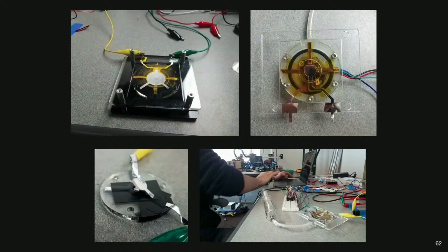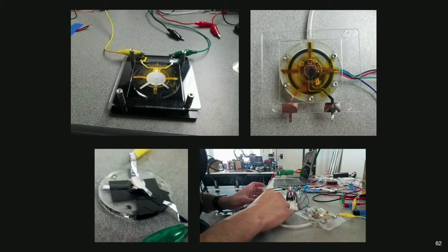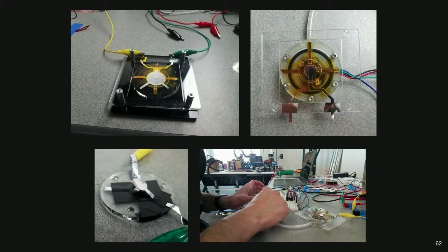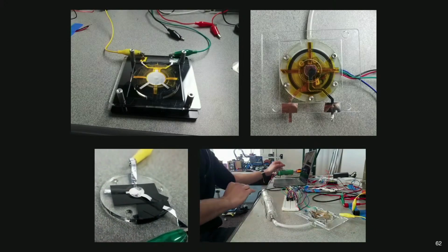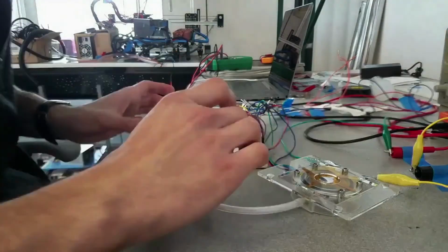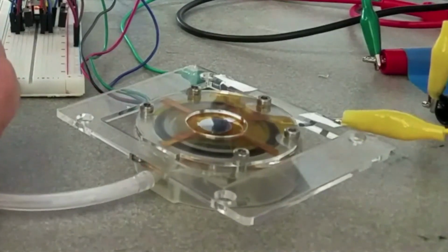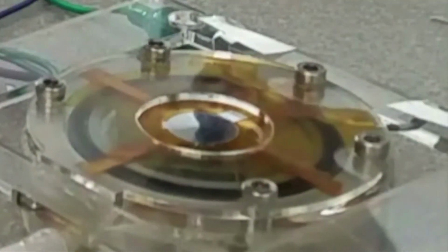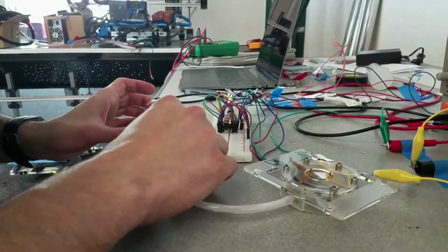Cool. Now, since this is the Hackaday audience, I wanted to talk a little bit about the process of getting here, because we're actually doing something that's a little bit unconventional with the valve structure. So initially our idea was to use these mylar diaphragms as lids. Here you can see I've got a very early prototype valve, and I'm trying to use this mylar lid essentially to block airflow. I'm using a syringe to pump air into this structure, and you can see it's not really working very well.